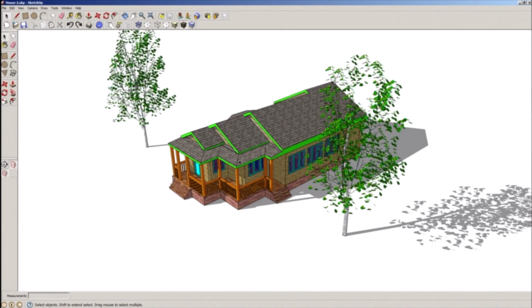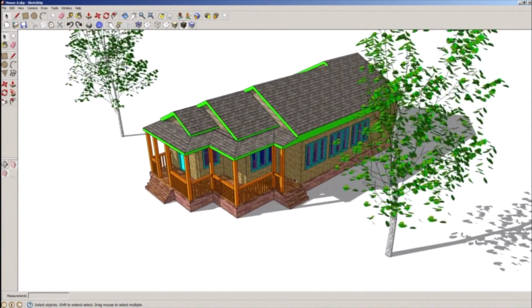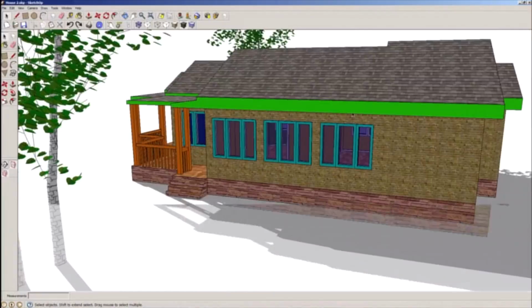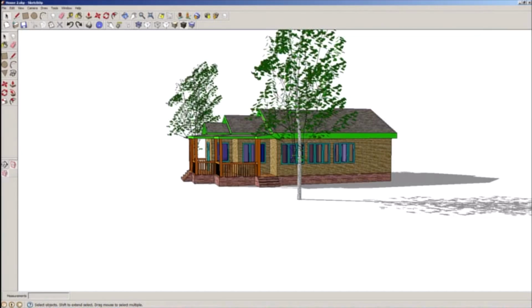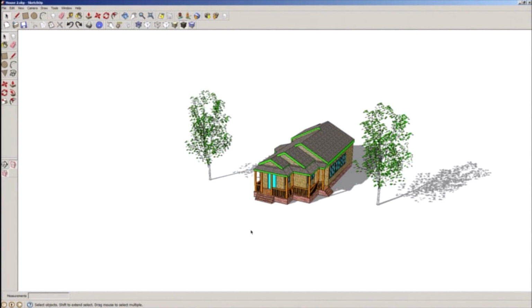The other category is just things that functionally you don't need in your project when you're working in the Visionscape client. In this case, that's going to be the interior of the building. You can see there's this entire modeled interior. We're going to remove all of that. You might also have a ground plane in your scene that you might want to delete. You might have a backdrop. You might have a pool that's recessed into the ground; you don't have a way of creating that recess in the client, so you're going to want to get rid of that.